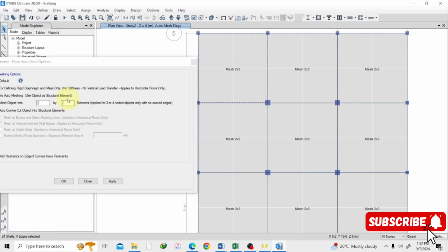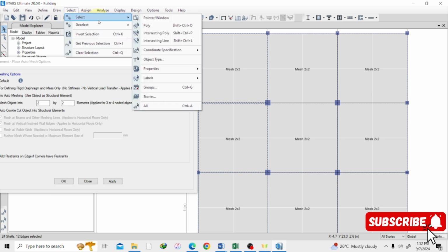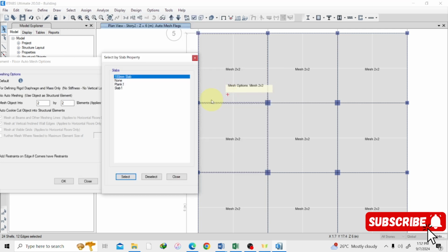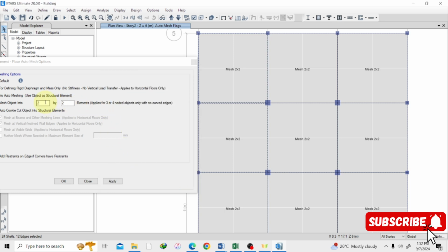I'm just going to select previous section, and it's going to select the slab. So select property type. So it's selected now. So let's try 4 by 4 and apply.